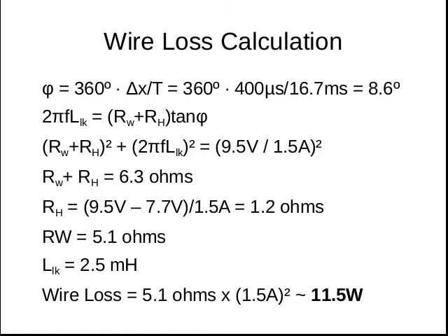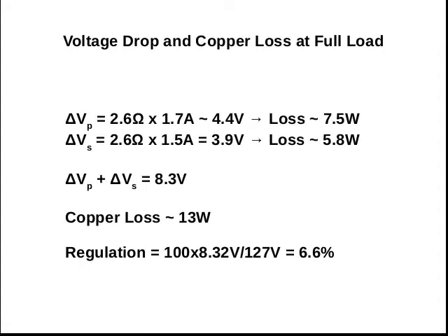Re-examining our preliminary guess, however, I supposed a load powered by the nominal secondary voltage and current at full load. That would require a slightly different turn ratio to compensate for the voltage drop caused by the wire resistance, and that would increase the primary current a little. Later I decided to leave the secondary uncompensated.